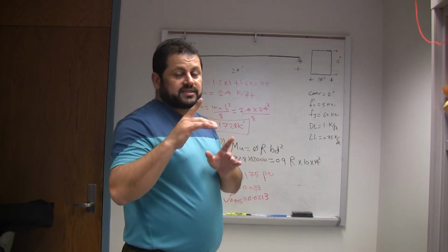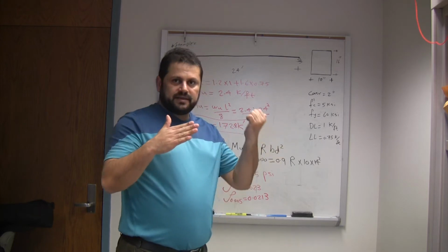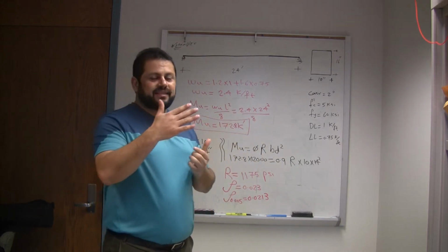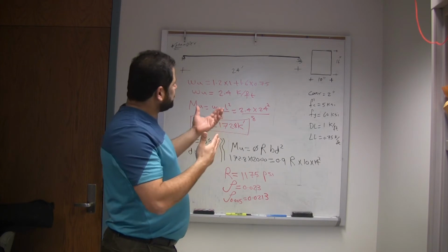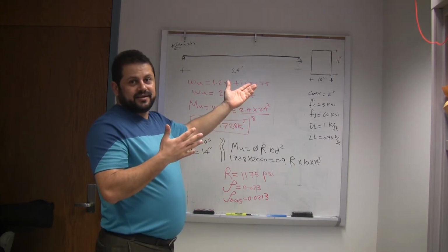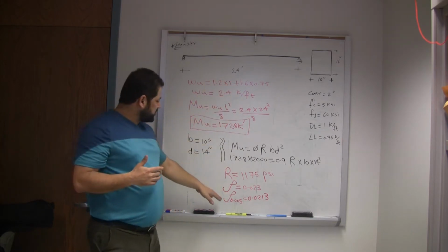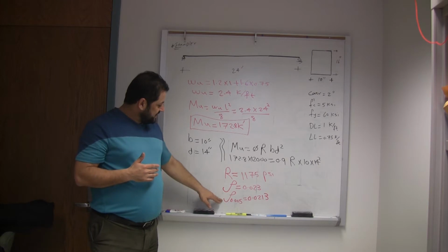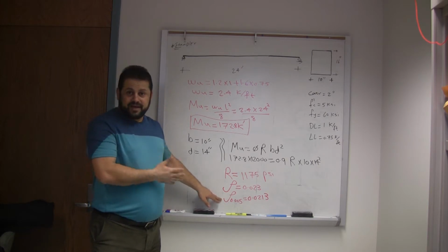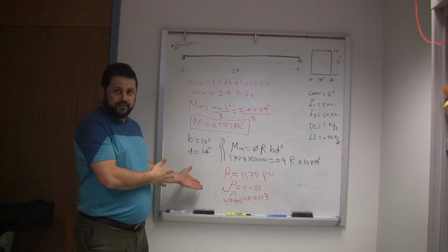I can go up to rho max. However, as you go with the steel now, you are decreasing the phi factor. You are gaining almost nothing. So in other words, you can say this design cannot be done as singly reinforced. We have to help with doubly. So rho 0.005, the maximum I can use is this number, or I can try rho max to show you. I'm going to show you now.